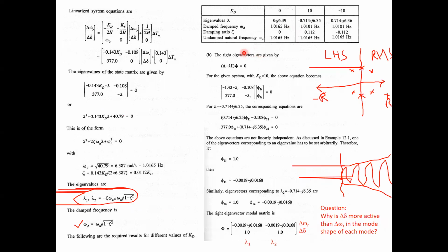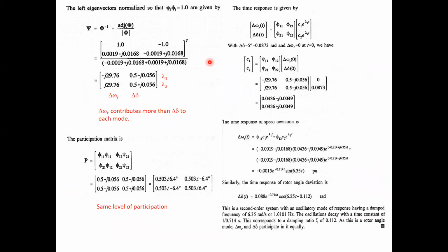So we have represented them in the form of a sum of a constant and an exponential term here. It is this way. And this is what they have considered, let's say, a small angle delta. Because in the first part, we had the steady state analysis, right? But the second part refers to the time domain. So if you want to analyze the system response in the time domain, you have to perturb it. That means around the initial steady state point, you have to consider this much change in the angle.